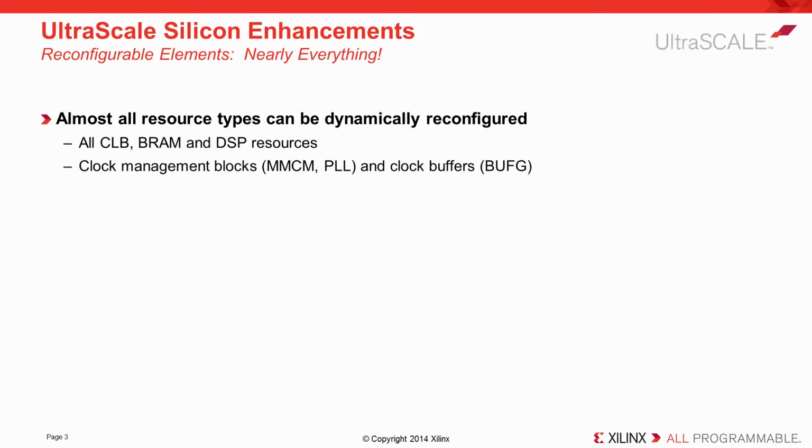Clock management blocks and buffers can be reconfigured on the fly, providing great flexibility for changing clocking characteristics as part of a partial bit stream. Gigabit transceivers can be reconfigured, enabling new possibilities for flexible network switch applications. And I/O resources can be included in reconfiguring regions, helping enable features such as field updates for tandem configuration.